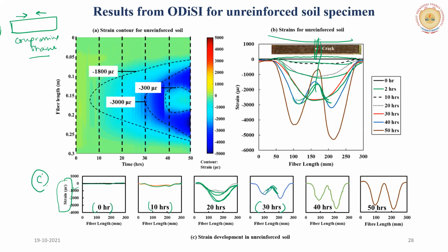So in the ideal case, what you can do is lay your fibers in the soil and monitor the strain occurring. By doing some basic tests, you know that a crack will develop at a certain strain. So if you see that this much strain is happening, you can take some remedial actions.